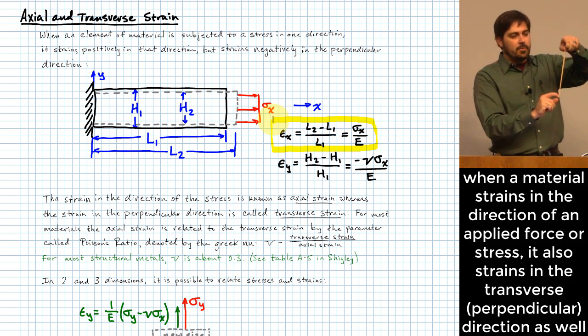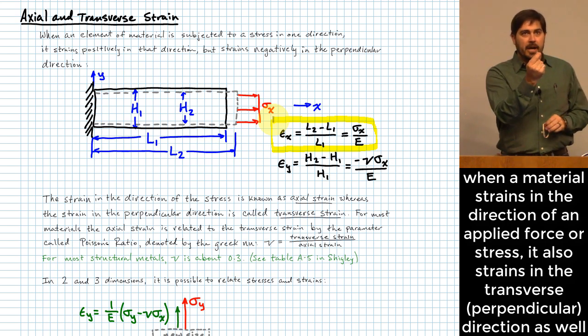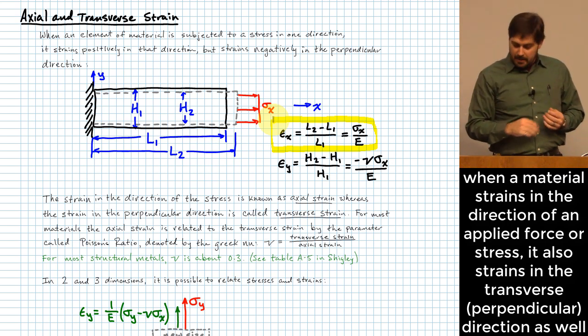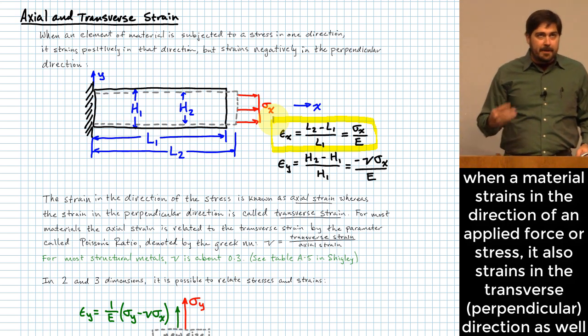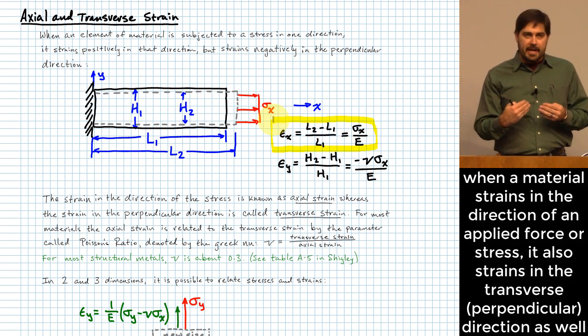As you stretch it, what happens to the rubber band? Okay? It starts out maybe a 1/4 inch wide here, and by the time I've stretched it a pretty good bit, it's probably down to maybe 3/16 or something like that. It has actually sucked down and become smaller in the direction opposite the direction that I'm pulling on it, okay? And this tendency of material to do that matters when we start talking about strain energy.